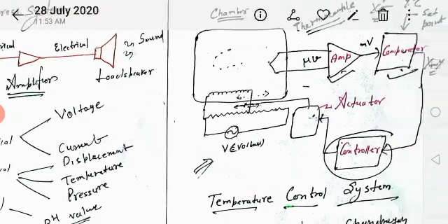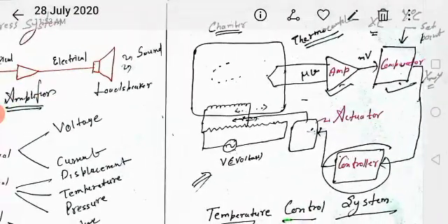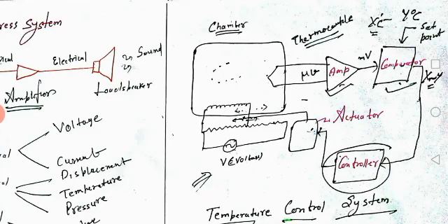And as an industrial system, we discussed the temperature control system in which the comparator and the controller were the core of the system, because the comparator provides the essential inputs to the controller, and on the basis of that input the controller decides the final action, whether it should move the wiper to the left or to the right. If the error is 0, then the controller will not move the wiper at all.